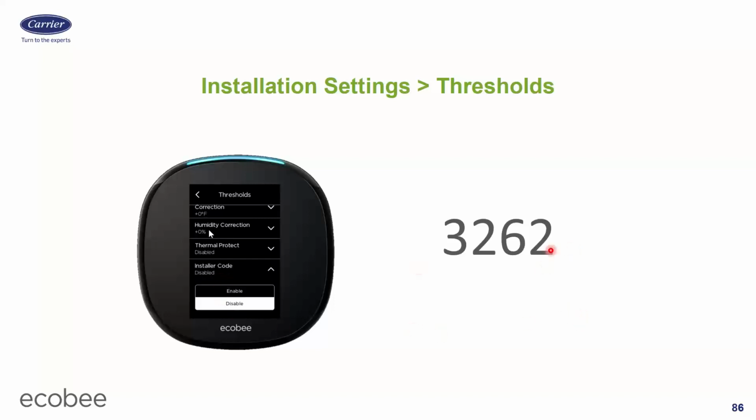So I would turn it on and I would lock them out if you're the one that just installed it. Now, if you're not the one that installed it, you just walked into the house to do a maintenance call, and they already happen to have an Ecobee, I would not lock them out in that case, because they probably already know about these screens and they probably been messing around in there. And if you lock them out, they're going to be like, dude, why'd you lock me out of this stuff, man? It's not your property. You can't do that, right? So if the stat's already there, leave it alone. If you're the one that just installed it, I would lock it out. And if they really want it to be unlocked, they can call me and ask me, and I'll help them. But I'd rather they think that they can't get into it.